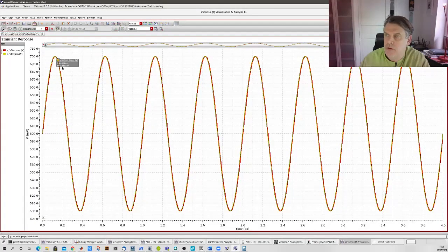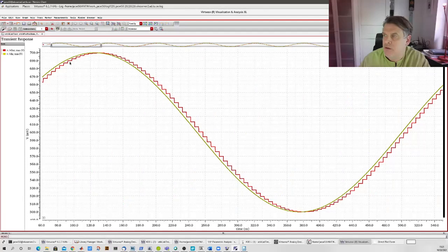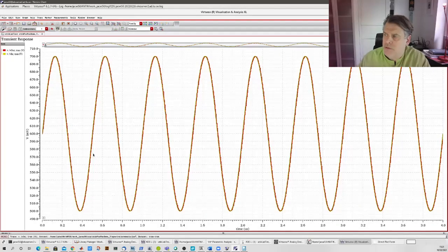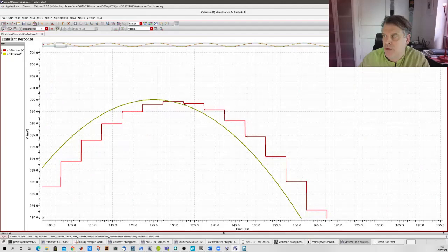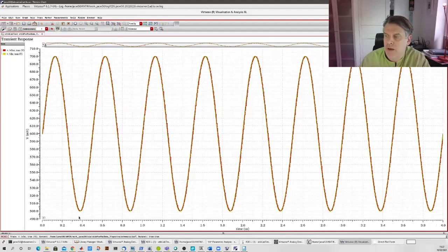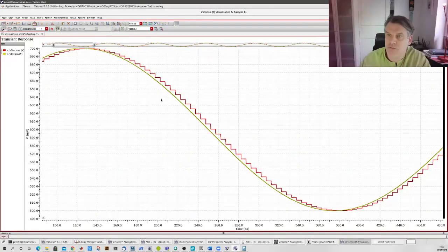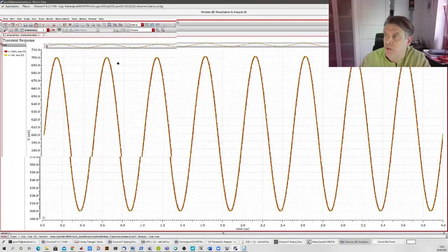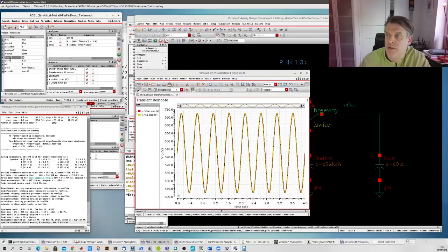Yeah, so in this particular case, we're running a pretty low frequency, so we're probably passing through this low pass filter without attenuating much, hardly anything at all. And there is hardly any phase shift either. You see the red output curve tracks the input yellow curve pretty well, so we're at a low frequency. We could try and increase the sample frequency. Here we see the sample frequency is 200 megahertz and the input signal is 2 megahertz. So let's lift it up to 20 megahertz.